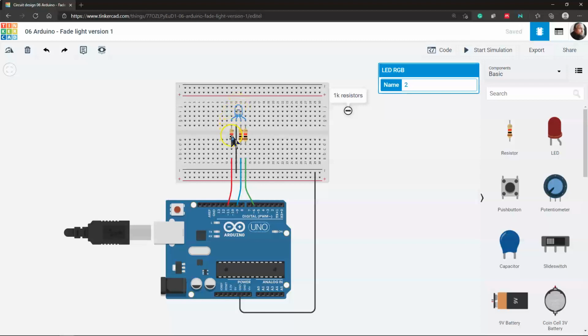So for this, we once again have resistors. This time I've set them up as really low at 1K. They're on each of the actual lines. So the individual anodes right here for, oh man, do not want that. Look at me just making a short circuit like that by clicking. So we have an individual here, we have the cycles, but now each one of these is then hooked up to PWM.